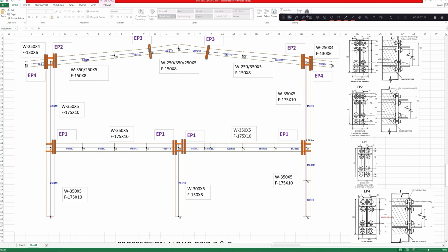Note this, at this point, this is the point where the column flange is of lesser width than the end plate width. So at this point the column flange has to be locally provided extra width like this. This will be a job of the fabrication detailer, but for information as an engineer you should know it.